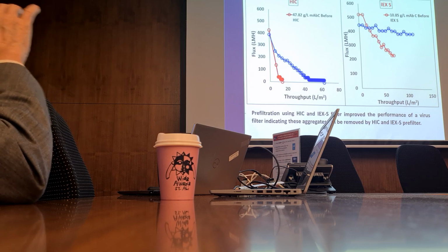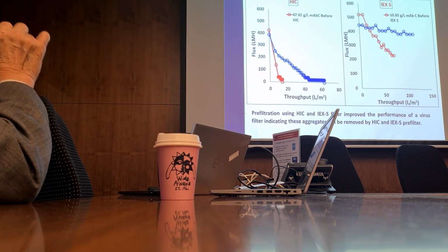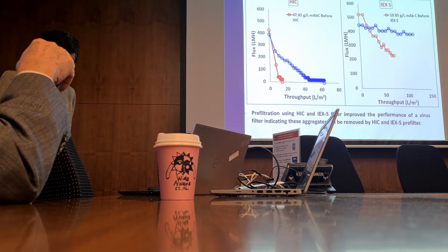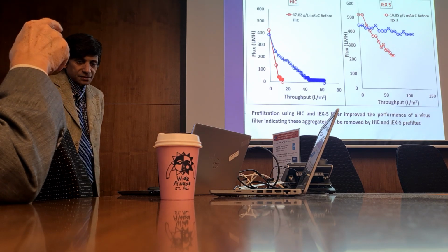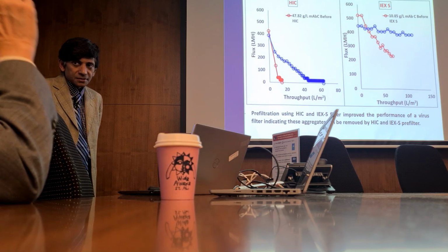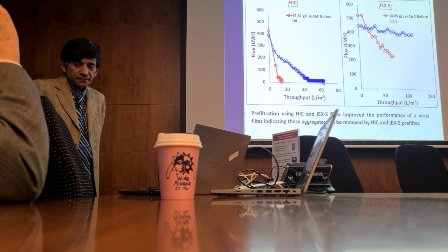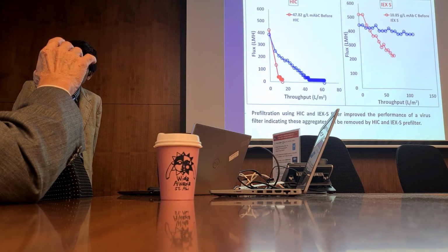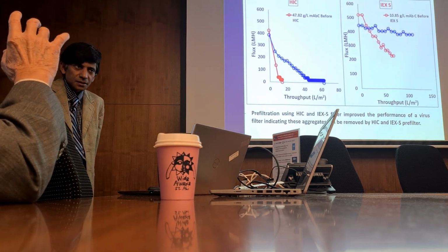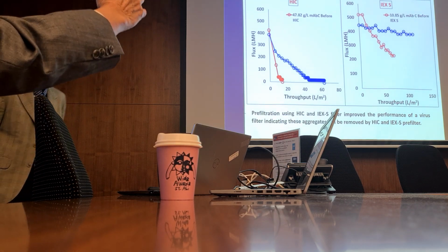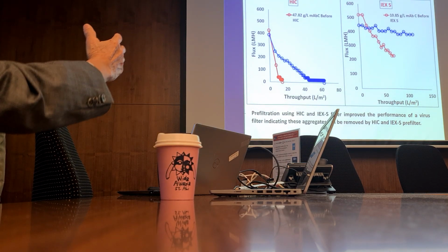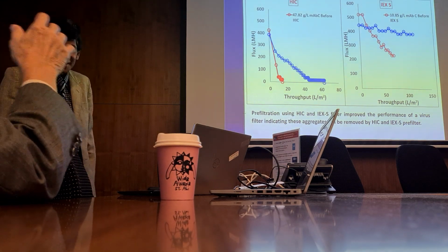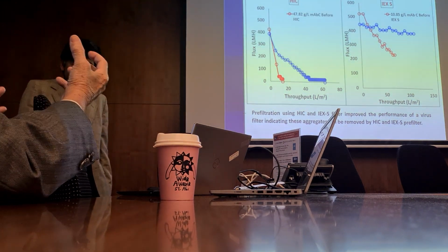For that application, you can control the pore size of the mica membrane very precisely. This is using an irradiation etching process, and you can get the pore size down to the smallest, if I remember correctly, somewhere in the order of about 50 angstrom. And you can make it bigger too. Do you know anyone who has used that? I don't know anyone who has used mica. In this case, it can be a very selective separation.